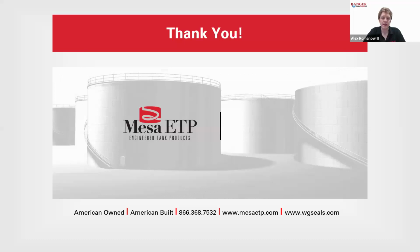Right. And we've got a similar thing in our CCME code here, and I've taken a couple of little pieces from it. Basically, for any tanks that are over 9 meters in diameter, which is almost 30 feet for you folks in the US, and if they're storing a VOC with vapor pressure equal to or greater than 10 kPa but less than 76, we're supposed to have one of the IFR, the EFR, or vapor control systems, and those systems are supposed to have an effectiveness of 95% efficiency by weight. So really, there's not a whole lot of room for error there, right?